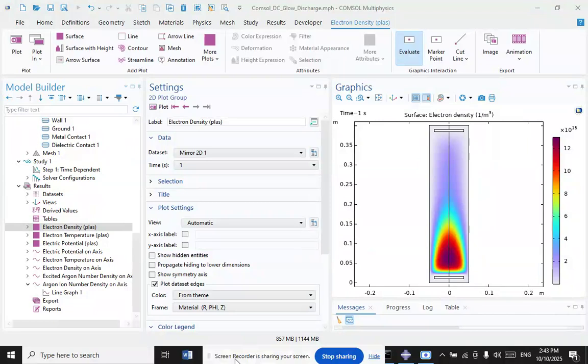A glow discharge is a plasma formed by the passage of electric current through a gas. It is often created by applying a voltage between two electrodes in a gas tube containing a low pressure gas. When the voltage exceeds a value called the striking voltage, the gas ionization becomes self-sustaining and the tube glows with a colored light. The color depends on the gas used.